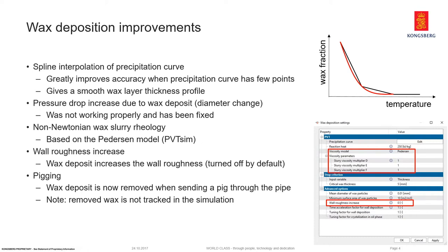And also we've implemented a non-Newtonian wax slurry rheology. So we're using the Pedersen model, which is what is used in PVT sim when characterizing your wax, so your waxy oil. So that is what is shown over here in the wax deposition settings.